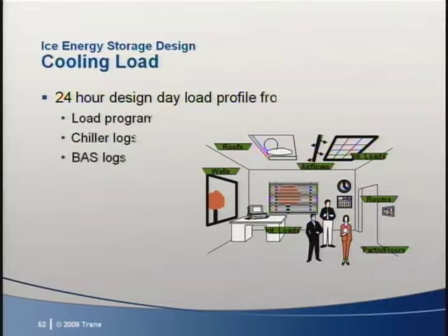Paul, would you take us through a couple different analysis tools to help us show why load data is so important? Lee, your comments are right on the money. We need the cooling load profile so we can select the ice storage system equipment to be used in the design and ultimately to perform the economic analysis. As Lee mentioned, the load profile can be obtained using a building load analysis program or operating logs and utility bills for an existing building.